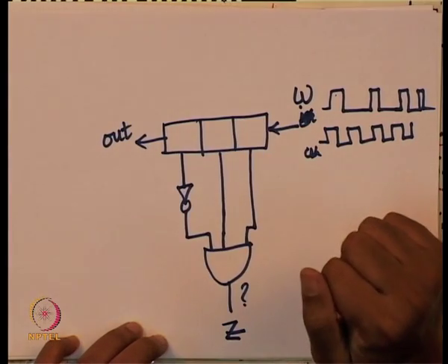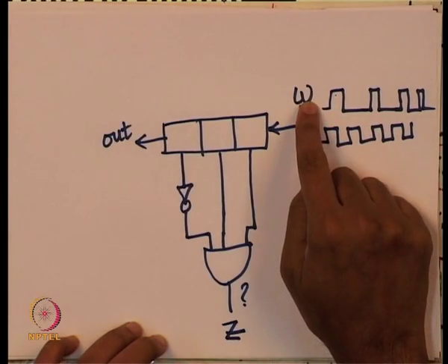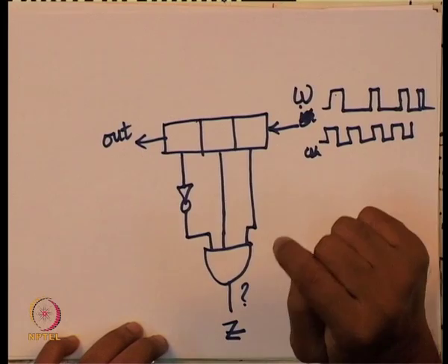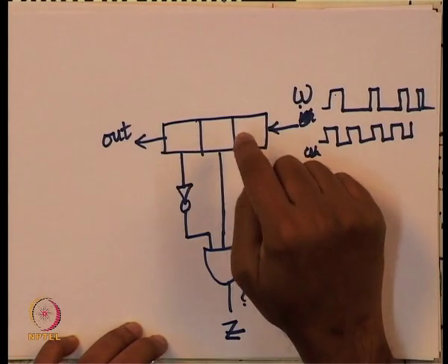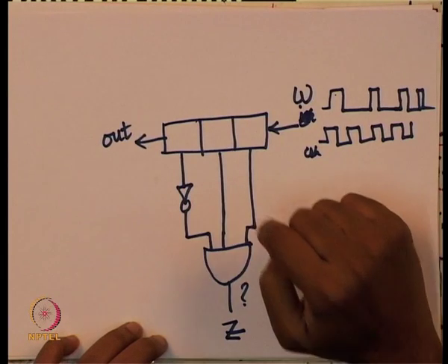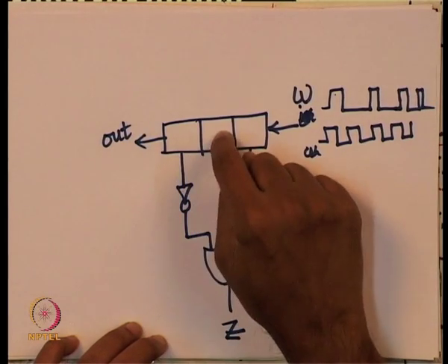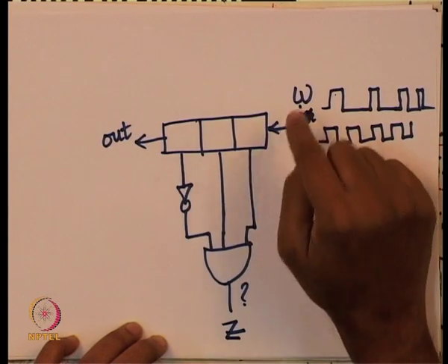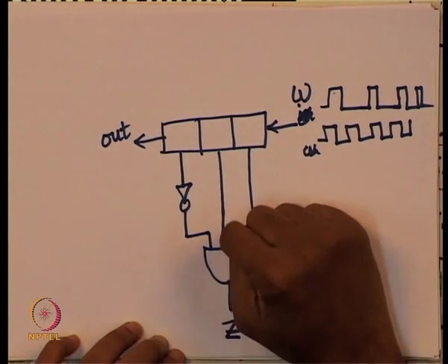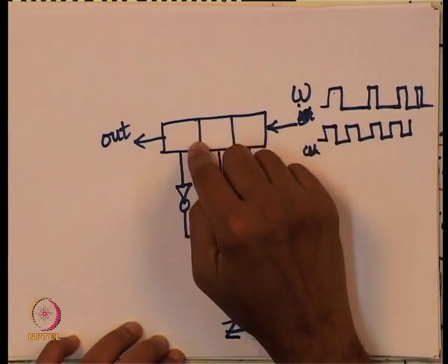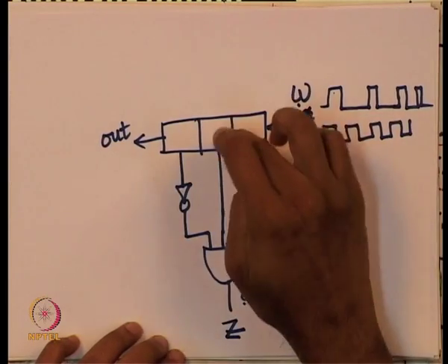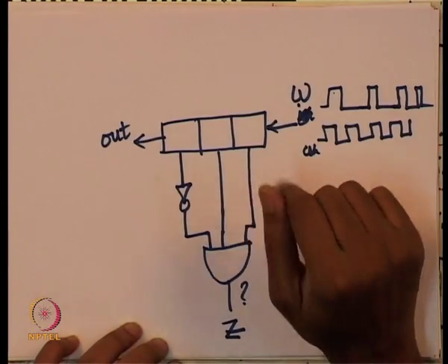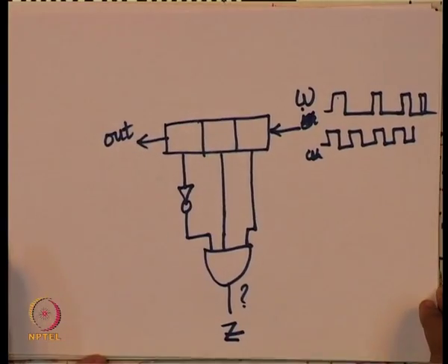It is not like a canonical sequential circuit, because the inputs are fed to the flip flops, which is okay, right. There is some logic connecting one flip flop to the other and so on. The output is a function only of the current states. So this is actually a Moore machine, right. The current input does not influence the output directly; the current input gets into the register and the register drives the output. So this is a Moore machine. It is a slightly degenerate case of the canonical model that I showed earlier.